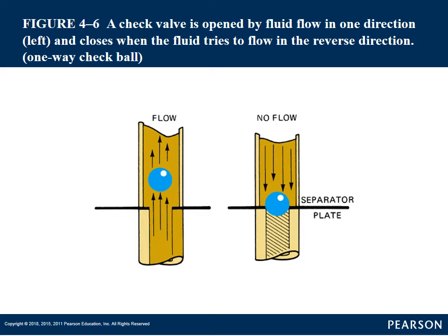In modifications, sometimes several things will happen. Sometimes in some shift kits, especially in performance shift kits, you might just take that check ball out altogether. So it'll apply through both holes. So it'll apply that clutch pack very quickly with a lot of pressure and hold that clutch pack very tight. And then it'll exhaust really quickly also. Or you can take and drill that smaller hole out a little bigger. So the fluid that's coming through the small hole is more than what it was originally.